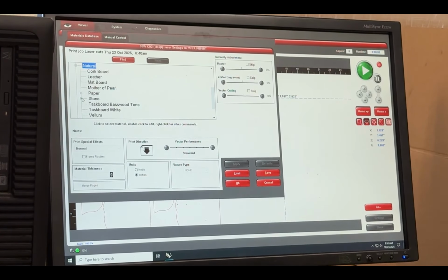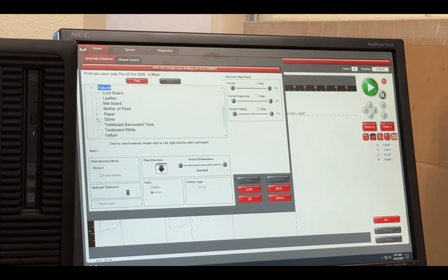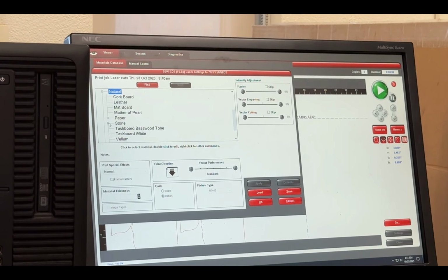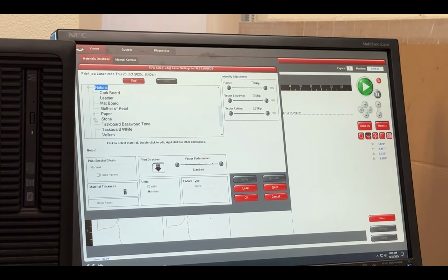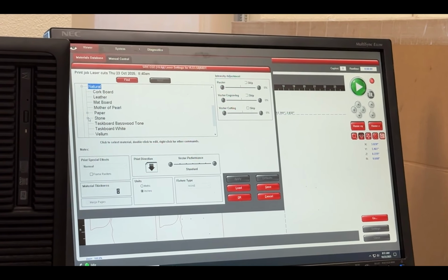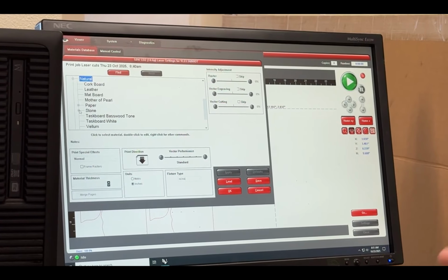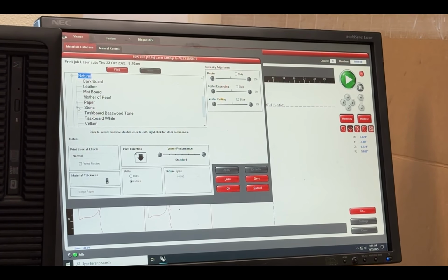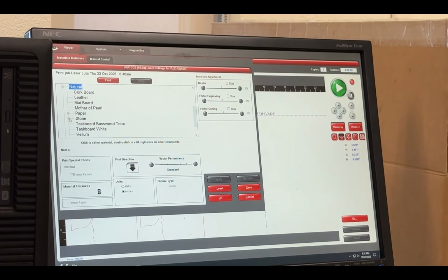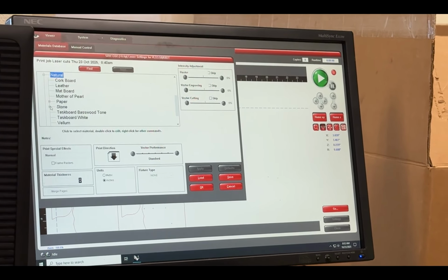Keep in mind that this isn't the strongest laser cutter, it's about 30 watts. And to be honest with you, the most that it can cut through is maybe 5 millimeters of basswood. And even then, it's going to cut super slow. So don't count on cutting 1,000 lines the night before your models are due, right? One thing I would say is, especially with the laser cutter, it does cut things really well and accurately, but at the same time, it's not always making a finished product. Usually you want to sand down basswood once it's cut, otherwise it looks pretty black, right? You also want to sand the top and the bottom because they'll be burned a little bit.